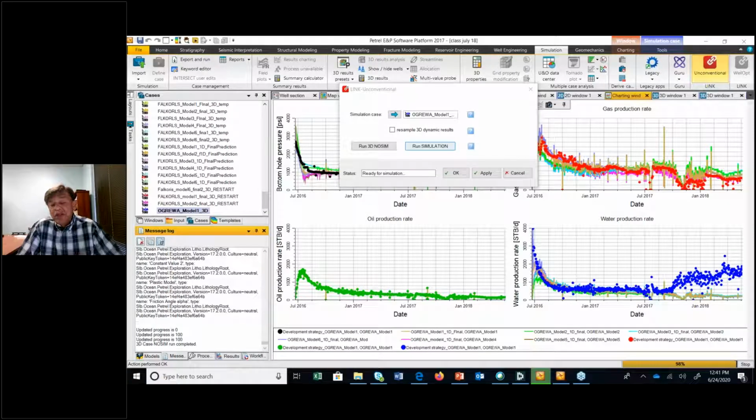So there are a lot of things which could vary within that 3D model. And what we are doing is that within each tau contour, we take all those physical properties and average them so that we can construct an equivalent 1D model. But because there is a significant upscaling of the physical properties, the match between the 1D and 3D model is not going to be perfect.